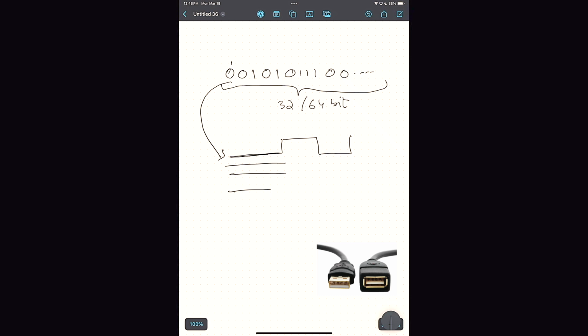Here there are only 4 wires in a serial bus, no matter what kind of port you are using, whether it is a USB-C port or a simple USB port. It's just Mac or Apple which keeps on changing their connector shapes, but everything inside is the same. So there are 4 wires only. One is VCC, which is the power, and the other is ground, and there are 2 wires in between, which are D positive and D negative.